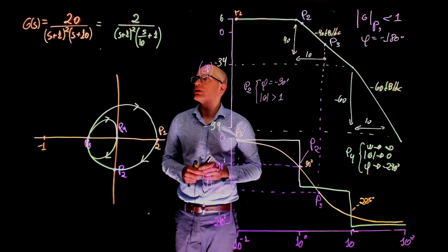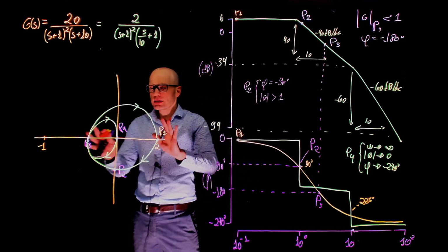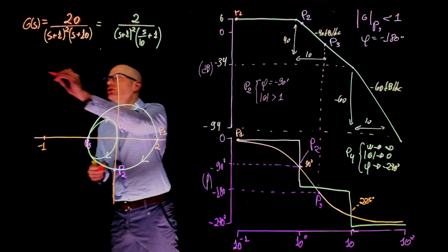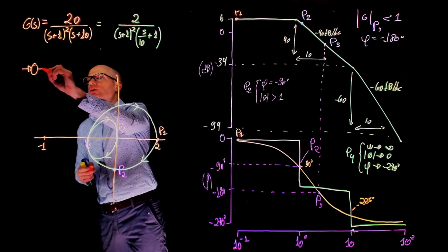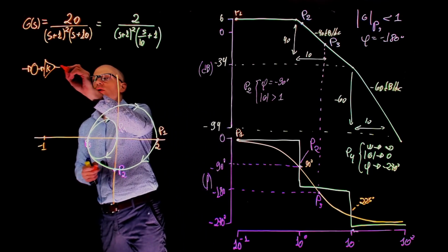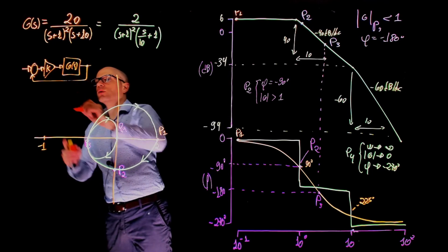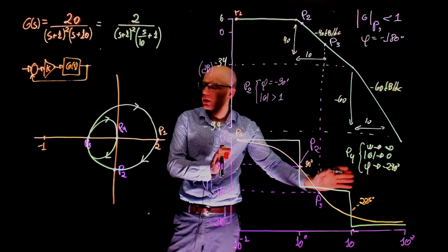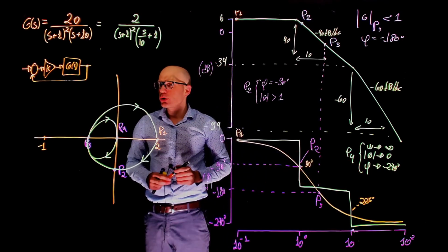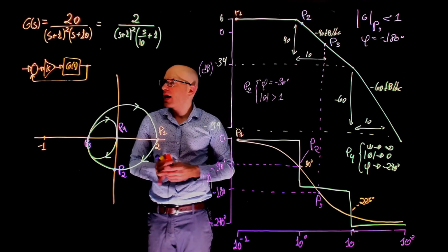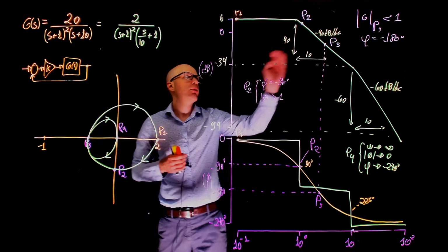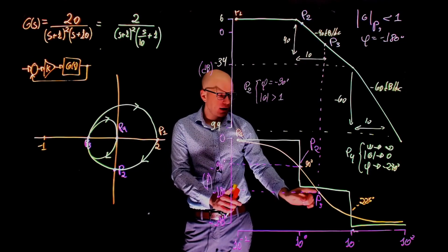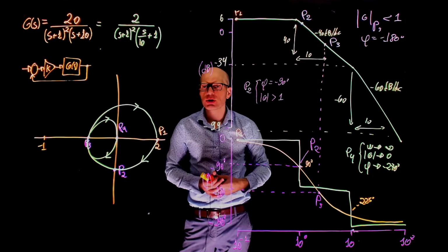So what can you conclude from this analysis? We can conclude that as it stands right now, the system is closed loop stable. Again, if we put G of s in a unit feedback loop, such as this one, when k equals 1, we have this Nyquist plot and we have this Bode plot. They are both closed loop stable. But notice that as we increase k, the Bode plot will go up and eventually reach the crossover frequency at negative 180 degrees. The system will be marginally stable.